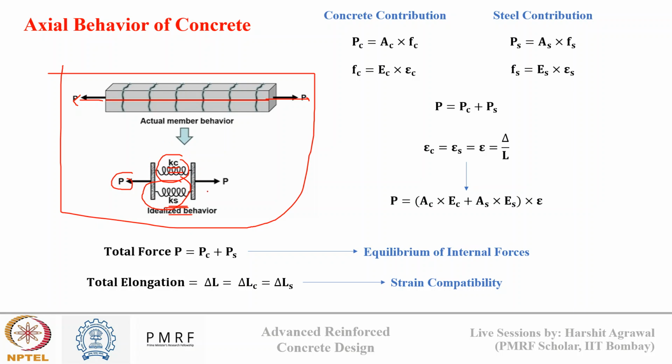So we can break down the behavior of reinforced concrete into two contributions. First is the concrete contribution, which will resist compression, and second is the steel contribution, where reinforcement mainly resists the tension or any residual compression after cracking.